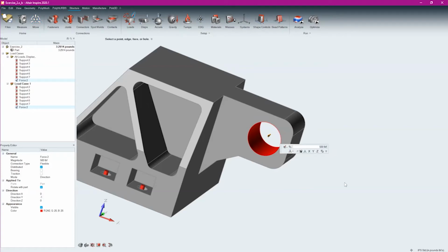If you don't know the angles of your force, but you instead know the components of a direction vector, I need only come here and open up this little slider right here. And now I can put in the components of my direction. See, right now it's pure negative y, so it's negative 1 y. By default, this is a unit vector. So if the components were combined, you would end up with a 1. And in fact, if I come here and orient this slightly differently, you see now I'm seeing the coordinates of that unit vector. I can put in whatever I want here. I don't have to simplify it down to a unit vector. I could come in and say 3, 4, 5, and have it orient that way as well.